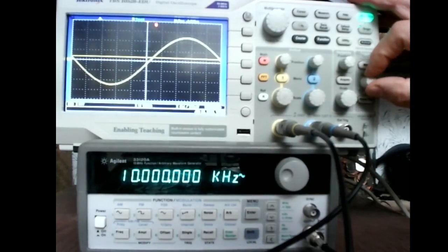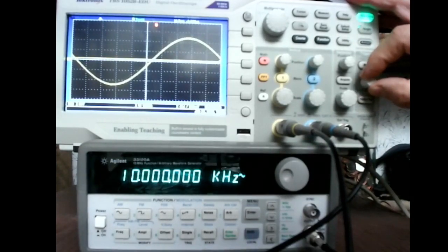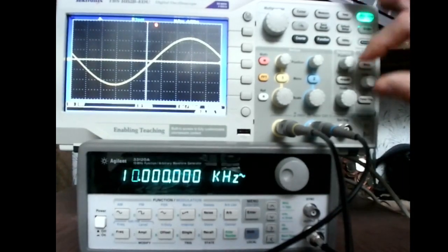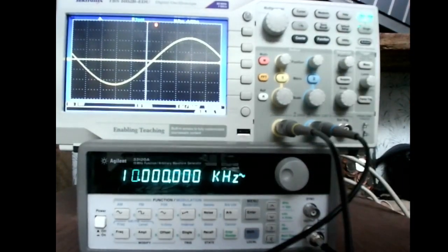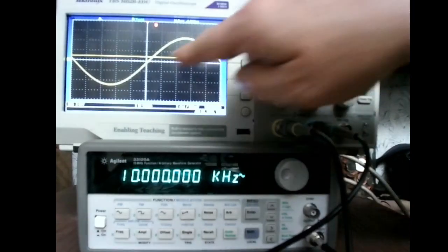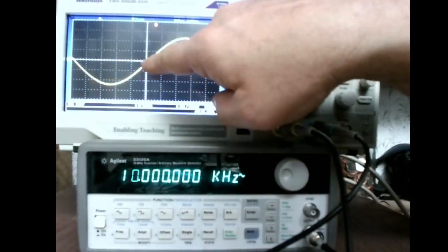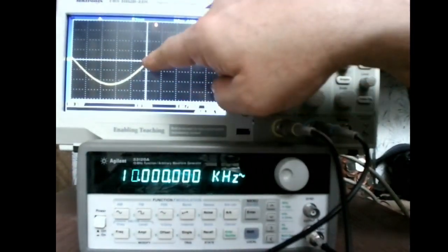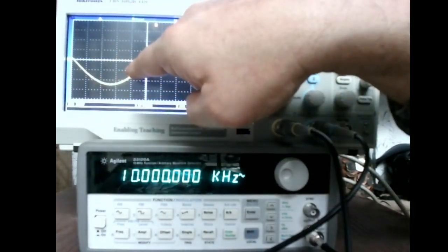Okay. Now if you set the trigger level right at 0, sometimes when it's noisy the sine wave will kind of move on you. So you normally want this trigger level to be up above the noise. The other thing is sine waves always start going positive. They don't start going negative.